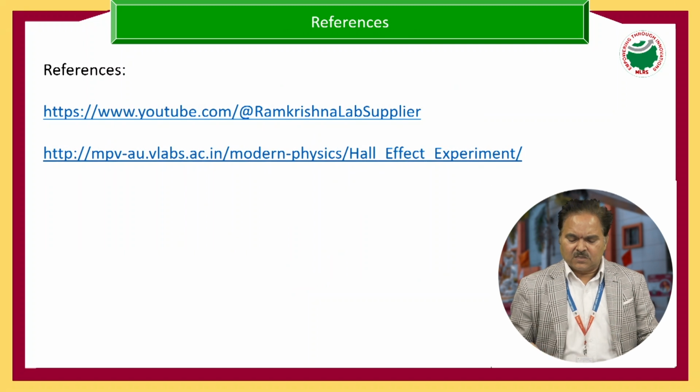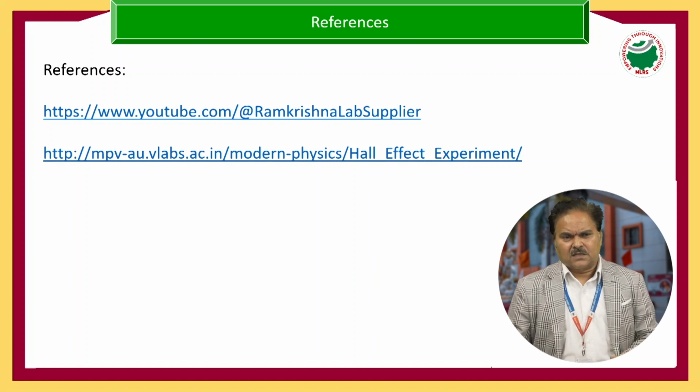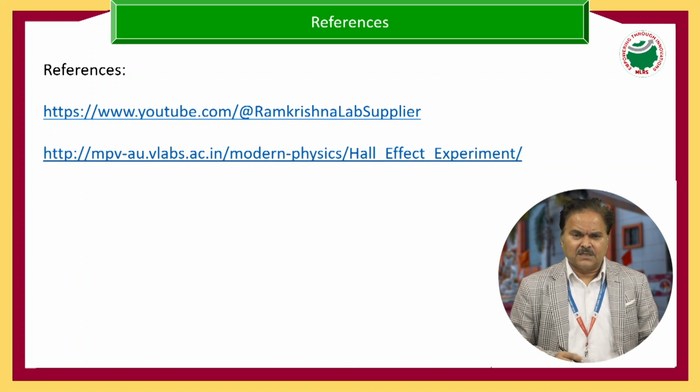Okay, so these are the references. I took most of these parameters from them. This reference value, and this Hall effect experiment, is very useful for the semiconductor industry. If you use pentavalent or trivalent dopants, we all know it may become N type or P type, but we don't know exactly how much concentration we are doping. Whether the dopant is going inside or not, we also don't know exactly.